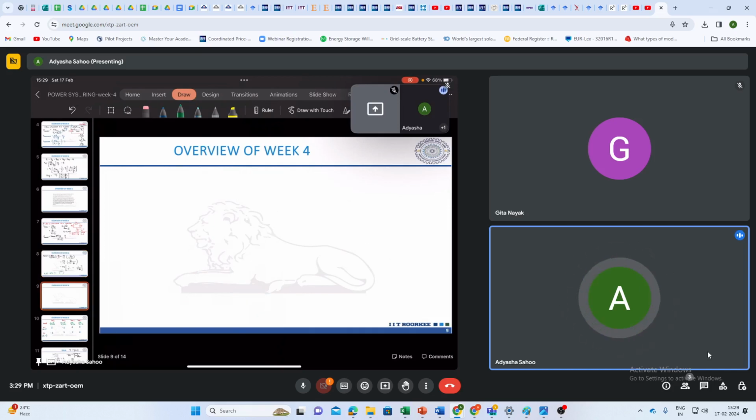Now once I have the expression for V transmitted of t as 2VF times 1 minus e to the power minus t by ZC times C, you see you have a capacitor here and you know the voltage across this is V transmitted.